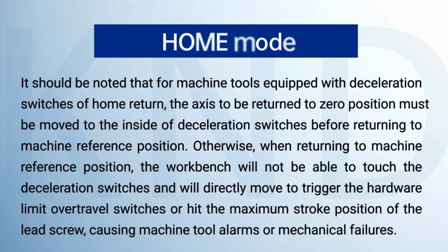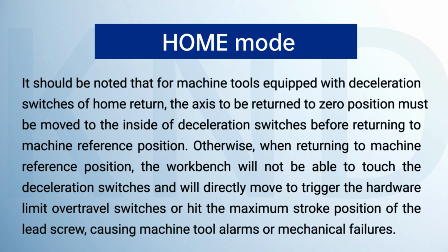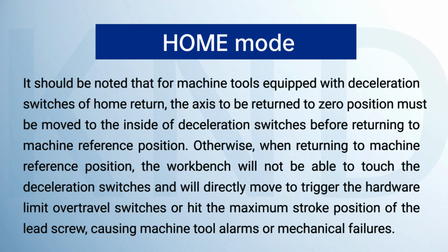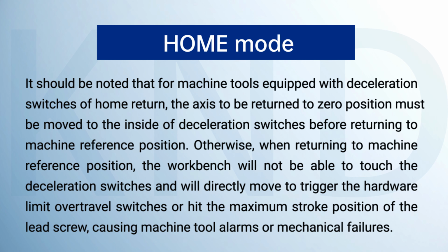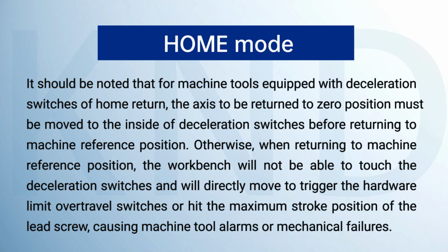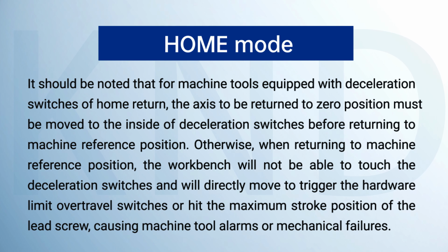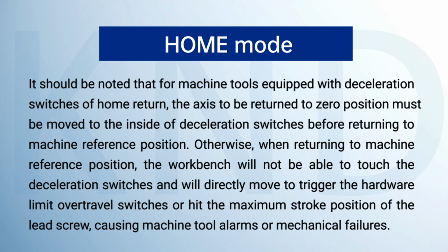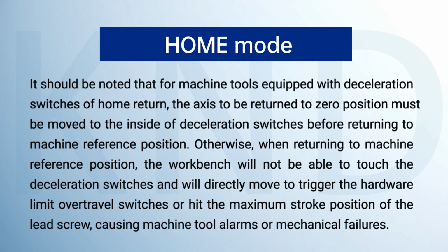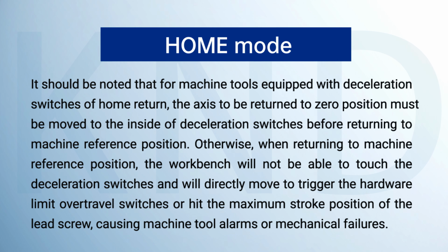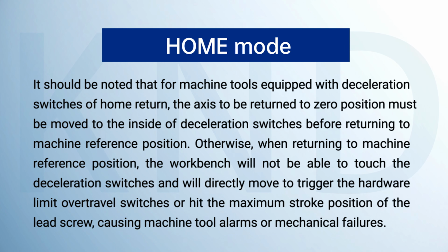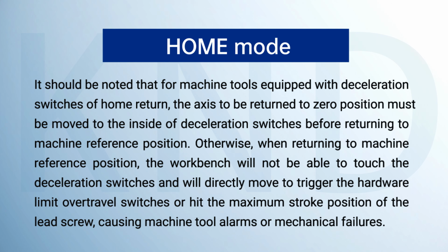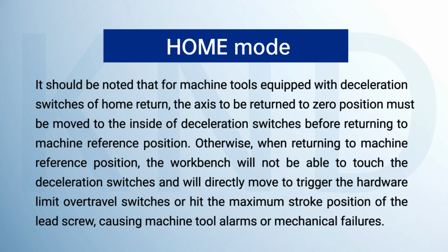It should be noted that for machine tools equipped with deceleration switches of home return, the axis to be returned to 0 position must be moved to the inside of deceleration switches before returning to machine reference position. Otherwise, when returning to machine reference position, the workbench will not be able to touch the deceleration switches and will directly move to trigger the hardware limit over travel switches or hit the maximum stroke position of the lead screw, causing machine tool alarms or mechanical failures.